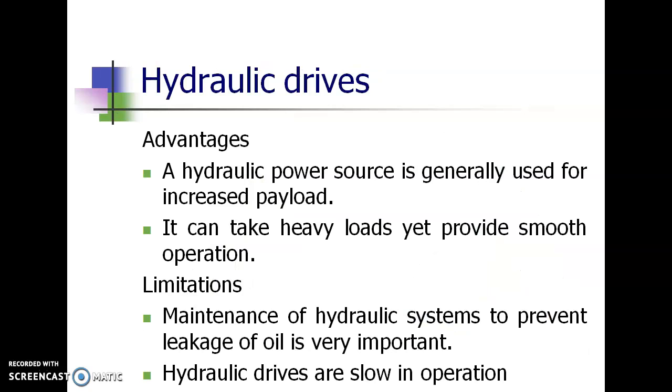What are the advantages of hydraulic drives? Hydraulic drives are generally used for increased payload, because the pressure we can develop using a hydraulic system is enormous. So the force we can obtain from the hydraulic drive is larger, and because of that we can use it for robots with larger payload capacity. Second, it can take heavy loads yet provide very smooth operation, because it is hydraulic oil, it can provide very smooth operation.